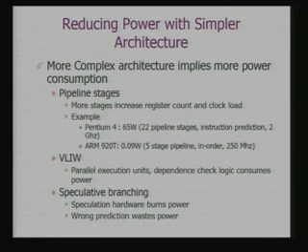In fact, Pentium 4 uses 22 pipeline stages. And if we compare ARM9, which we have studied, it uses a 5 stage pipeline. And these figures that we are seeing here, one is 65 watt, another is 0.09 watt. This is not only because of the pipeline, but because of other factors as well, I shall come to it, but pipeline is one of the major factors which affects the power consumption.